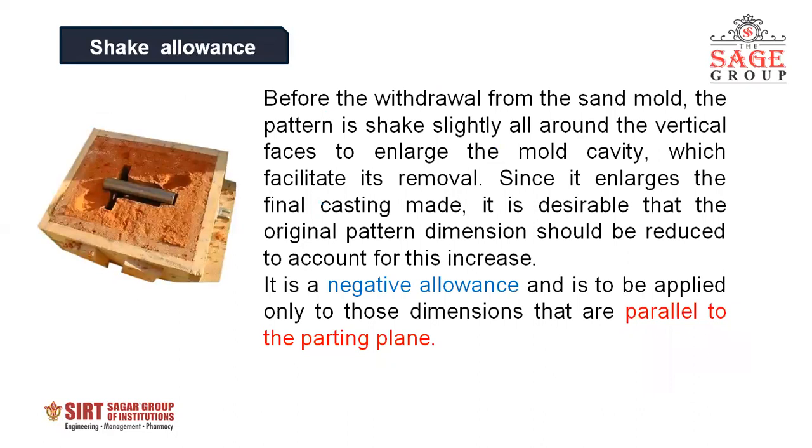Shake allowance. Shake allowance is because when the pattern is embedded in the sand and we have to eject it out, during the ejection process, it shakes slightly and enlarges the mold cavity to facilitate its removal. So in the pattern, we have to take care of shake allowance, and we have to reduce the dimensions of the pattern accordingly. It is a negative allowance.